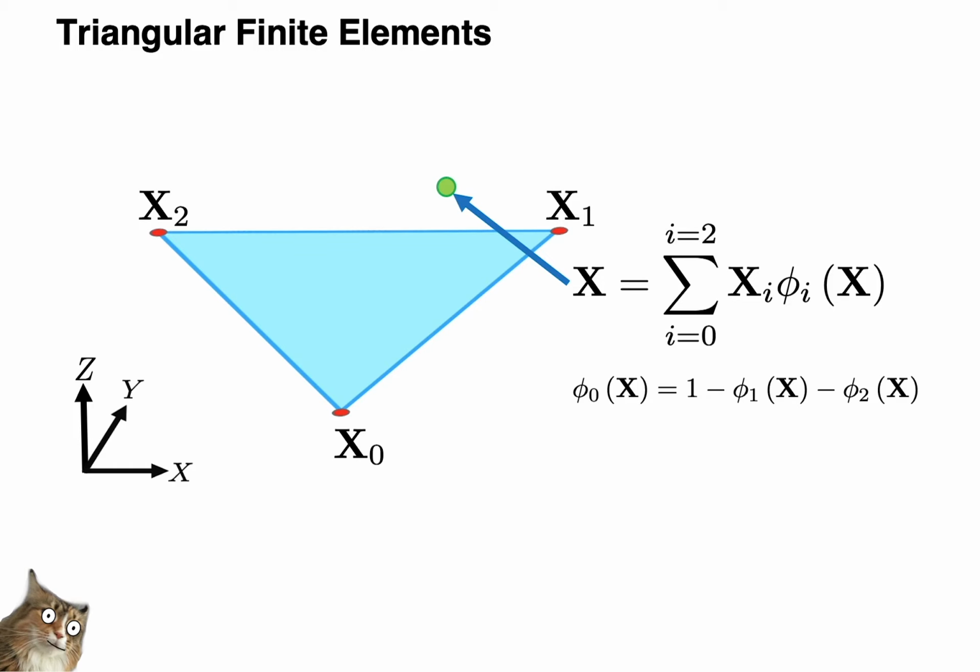The current problem setup is going to make it difficult to exactly solve our equation for the phi functions, so we'll have to get a little creative. Rather than try to reconstruct the reference coordinates of points off of the triangle, we'll aim to reconstruct the reference coordinates of the nearest point on the triangle itself.